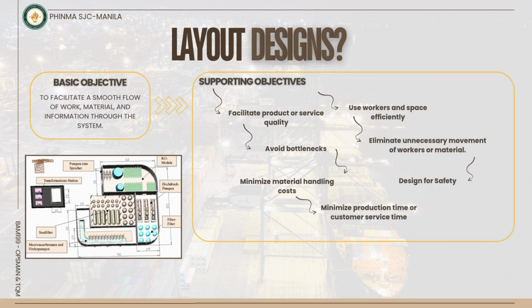So, layout designs give these objectives: minimizing the production time, making sure the layout safely processes the products and is safe for the employees or staff, making sure the space is efficiently used, and most specifically that the skill of the workers is properly used whenever they are stationed from one station to another. At the end of the day, it's the product or service quality they're looking into.